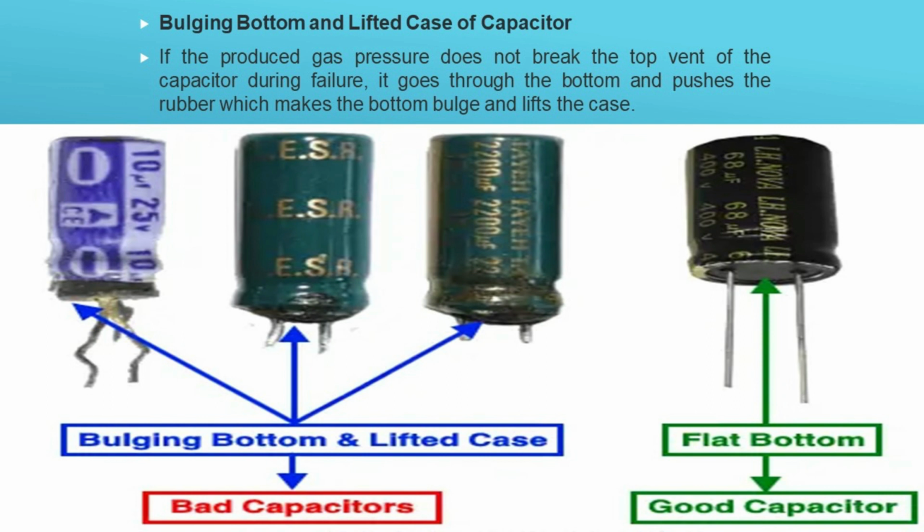Method 6. Test the capacitor by continuity test mode. In the DMM and AVO meter, the continuity test mode can also be used to check whether the capacitor is good, open or short. To do so, follow the simple instructions below.